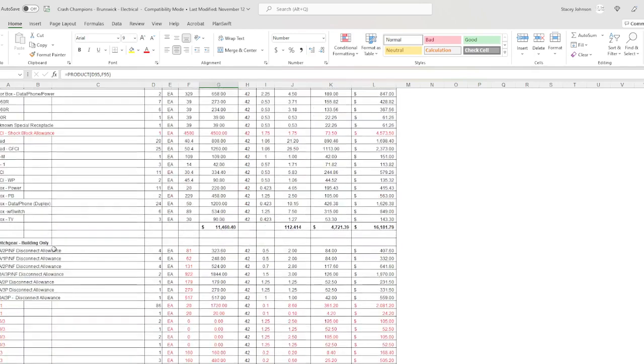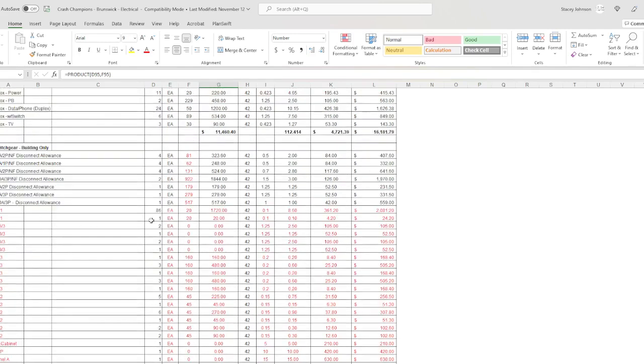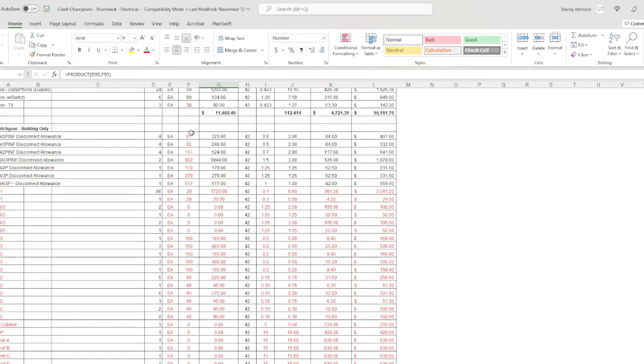And then everything in the switchgear portion for me is everything in the single line diagram and all of the disconnects and all of the breakers. Okay, and so you get these numbers by counting the breaker panel, and I've got this many of that, good counting tool. And then the cost book will give you a pretty good, for all of your disconnects and all of your breakers and stuff, you can go by the cost book. They give you a pretty good, up to a point. You see where I have zeros. So up to a point,